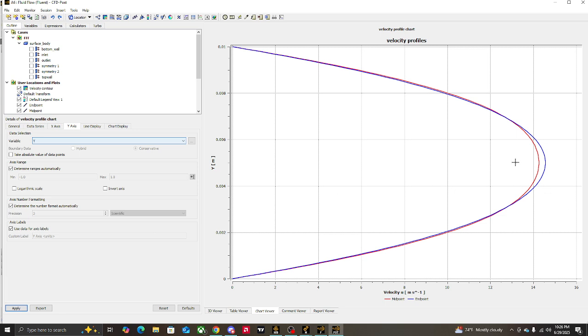Nice, cool. So here it shows you the midpoint line that ends earlier than the endpoint line, right? You see how velocities form sooner at the midpoint than they do at the endpoint. You have two different velocities at each point. One is underdeveloped, the other one is more developed. The endpoint being more developed, right?